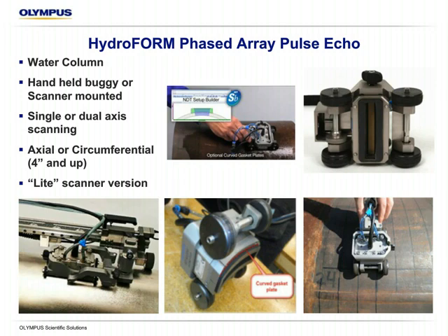The reason we use water in this application is it offers the best ability to couple to the surface, especially on rougher in-service surfaces, where the surface condition even after UT prep might not be perfect. So water offers a great medium for that, and also pretty good near-surface resolution, which we'll talk about collectively a little bit later. We're able to change these plates out. After a period of time, if the gasket gets worn out from scanning or running over some spatter or something like that, it's a toolless design. We just have extras of these in the kit. You slap a new gasket on and continue to go.